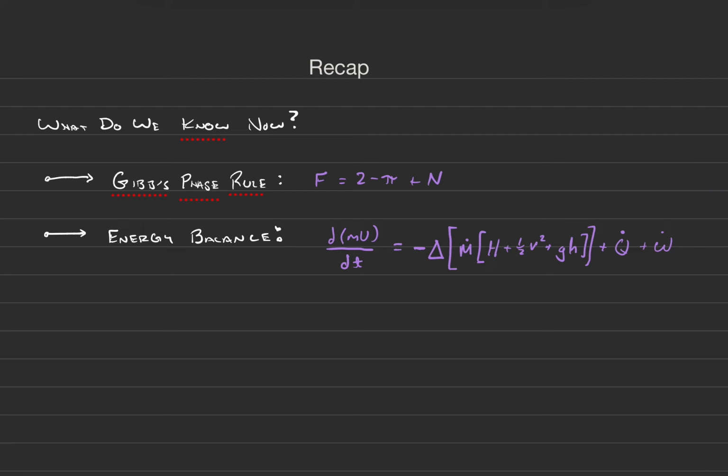Now, this doesn't take into account heat changes as a result of reactions. This solely takes into account changes in internal energy as a result of heat and work, plus the flow streams and the energies that those flow streams have. So again, those bracketed terms had to do with the flow streams going in and out. And then the dotted terms, the Q and the W, have to do with what we called the non-physical, or non-flow-stream, transfer of energy. So, to be specific,